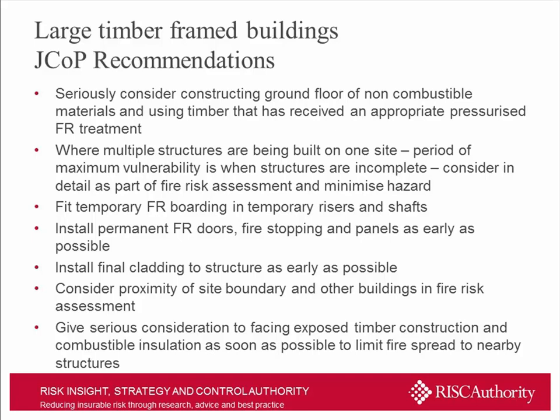So the Joint Code makes recommendations for fire safety in large timber frame buildings, which start with constructing the ground floor or the lower floors of a non-combustible material, so reinforced concrete, steel frame, something of that nature, where the potential for fire is significantly reduced, and also using appropriately pressurised treated FR timber. Can't be enforced, but that's certainly what the code requires.